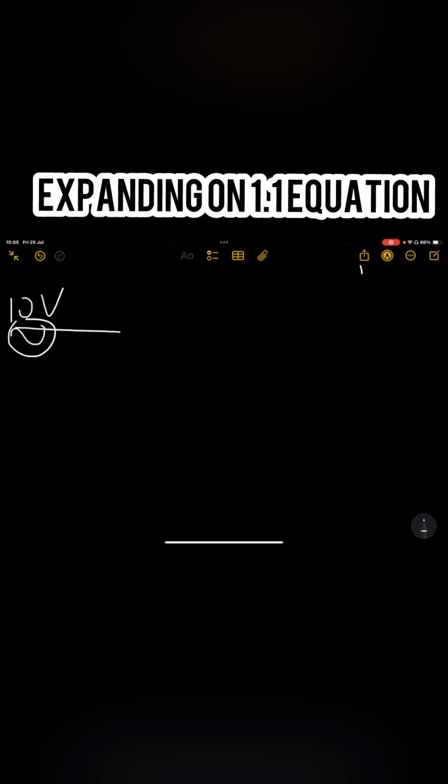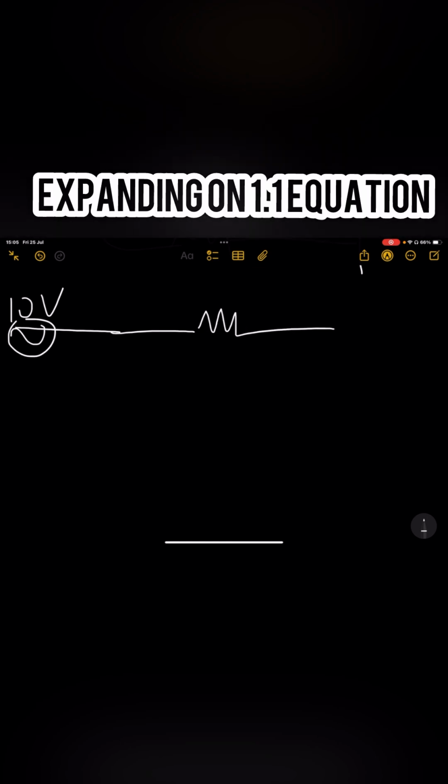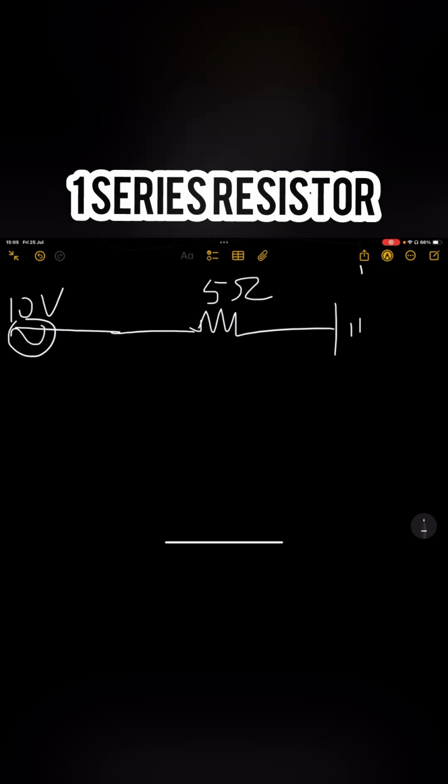Right, now let's look at, again, the 10-volt source feeding a resistor. This is ground. So let's make this a 5 ohm resistor. Now, according to Ohm's law, this would pull 2 amps. Why 2 amps? Because V divided by R is I. This is one of Ohm's law's principles. So V divided by R is I, which is 2 amps. Simple.